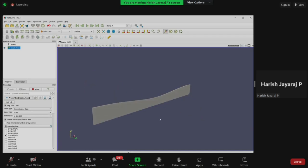This is just one small wedge of a nozzle. If you can imagine, the nozzle is a circular or say cylindrical kind of revolved geometry, but it is uniform, right? So whatever the flow is happening, it's going to be the same along all the sides. If we just take a slice of the wedge or a small section, it is going to be the same throughout the nozzle. So if we just get the values around here, it is enough.